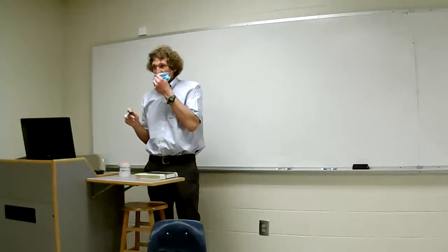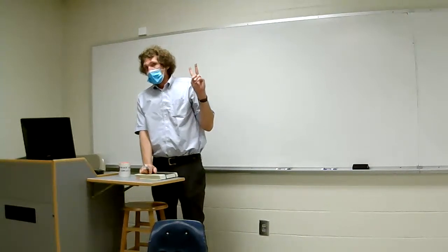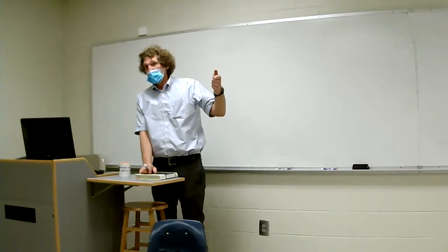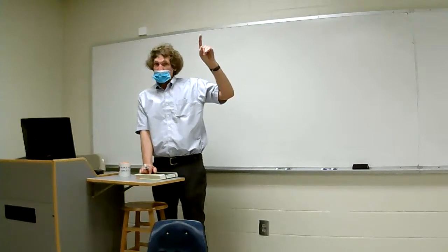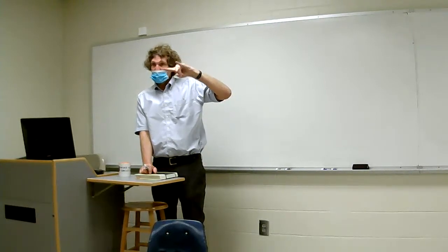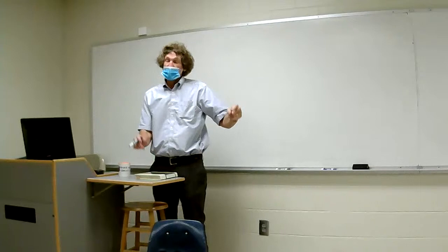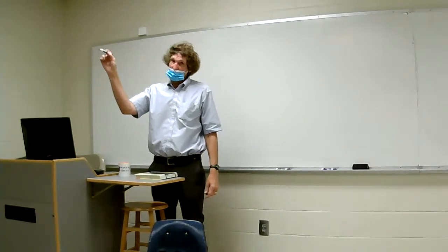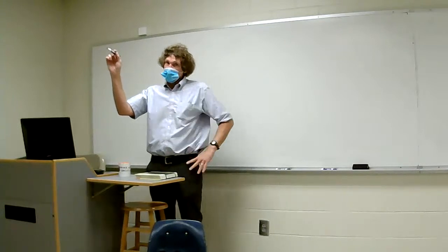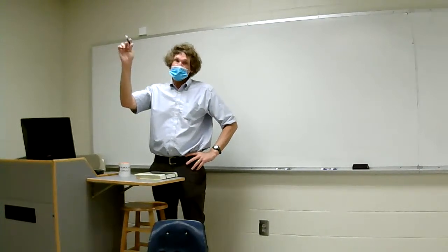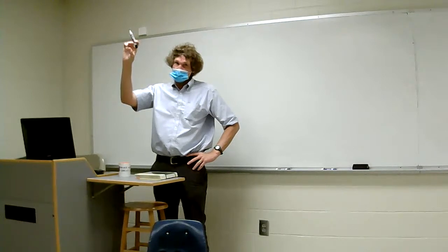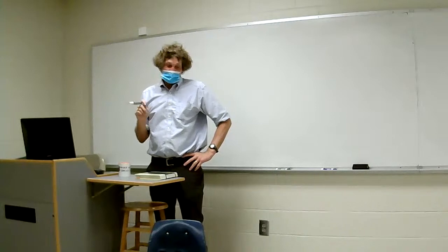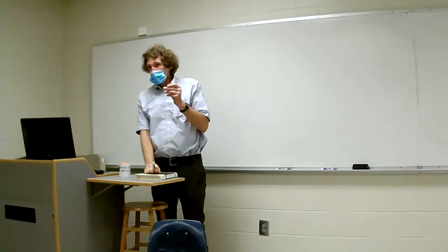Now, what I'd like to do is cover two things in a little more depth. I gave you the thing about EMC in more detail, right? You remember the waveforms? We have a rise time, fall time, then we have an on time and T, and I showed you what the actual frequency response was, right? You got a certain plateau, 20 times the log of the duty cycle times the magnitude of the pulse generator, divided by 10 to the minus 6 for microvolts, dB microvolts.